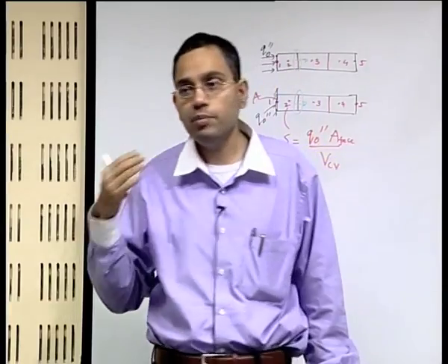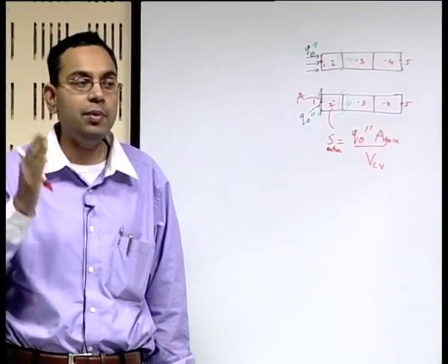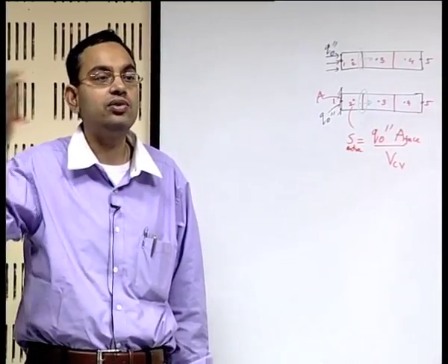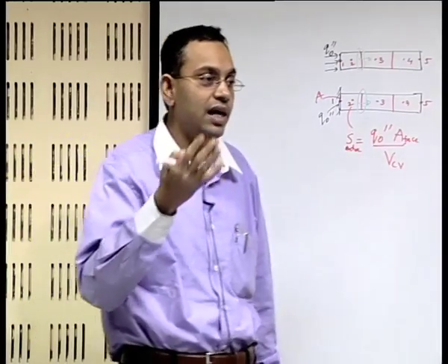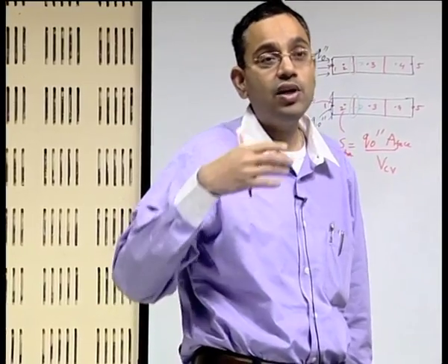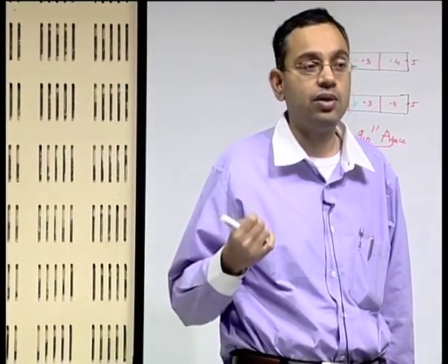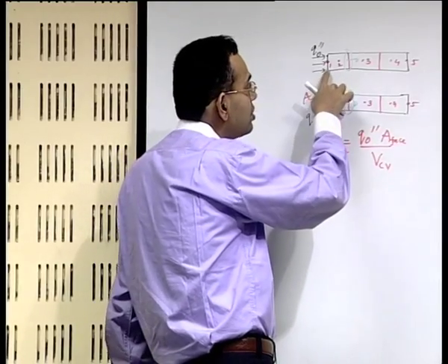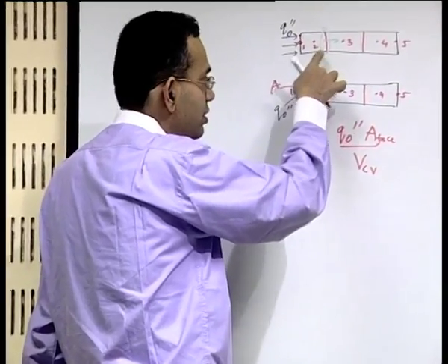By mathematics you are allowing the boundary condition to propagate inside the domain, and that is how your domain knows that there is a boundary and the boundary condition has been imposed. The more rapidly you can do it, the more rapidly you can converge to the actual solution. So, here this flux is at the boundary, but it is not penetrative inside the control volume in one shot.